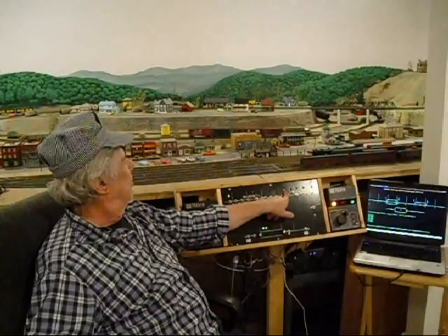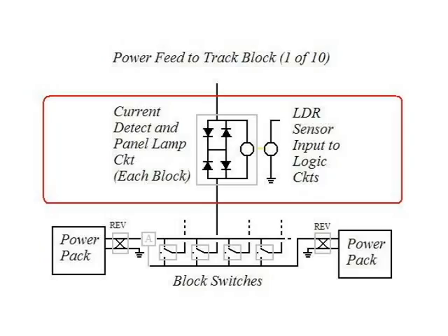The tracks are routed through what they call a current detector. Now, a current detector, for those with electrical knowledge, is nothing more than a bridge rectifier, and it's wired in such a way that the current goes through 2 of the diodes this way or 2 of the diodes that way. And diodes have a voltage drop of 0.7 volts, so that 2 of them ends up being 1.4 volts.